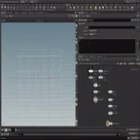And let's refer this to channel F. There we go. We're going to be setting the prim cost attribute. So f at prim cost equals this. All right. And now we have a nice channel to set this attribute. And if we go into our geometry spreadsheet, so new pane tab and geometry spreadsheet, you can see our primitives have a prim cost.